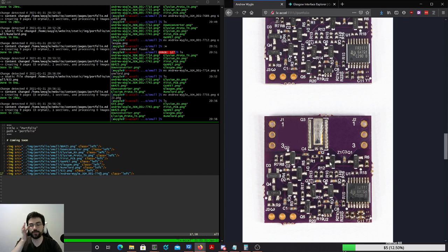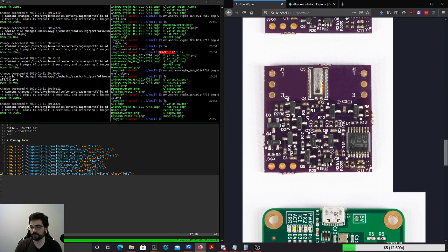And so you get solder paste, which is basically little balls of solder embedded in a flux material. You just squeegee it across the stencil, and it deposits a uniform thickness of solder across all of those pads. Then you place the components on top of that solder paste and bake it, and the solder melts and the joints form. So this is how all automated assembly goes. If you're doing densely populated surface mount boards, you want to use this workflow. It's way, way, way better than trying to do everything by hand.